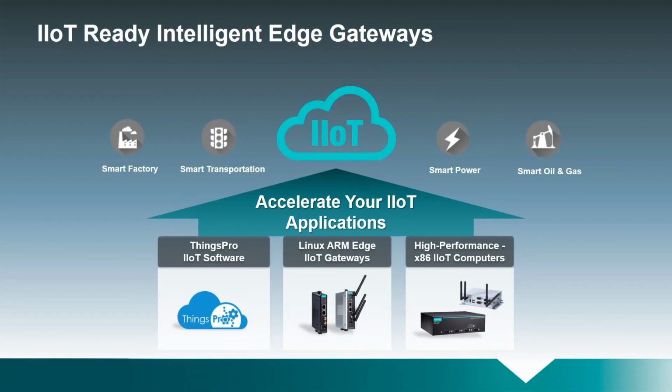So if both of these architectures exist and will continue to serve their respective applications well, can you have coexistence between them? The short answer is yes. A new product category of IIoT edge gateways has emerged, and these products provide that bridge from polling to publish-subscribe architectures and the APIs we're now using in the IIoT. Moxa has a full product offering here with Linux or x86-based computers and software that enables device management, connectivity, and protocol conversion, both from industrial protocols and to publish-subscribe APIs like MQTT, AMQP, and native cloud communication and configuration options.